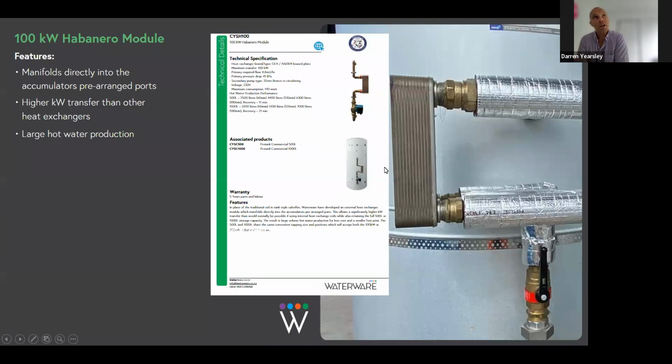Hydraulically, the water we keep in the heat pump is indirect. It's like a mechanical based system where the water that's in the heat pump and in the buffer tank is kept separate from the water that's inside the hot water cylinders. We do that with a high capacity plate heat exchanger. So the water that's in the tanks never actually passes through the heat pump. It's kept separate.